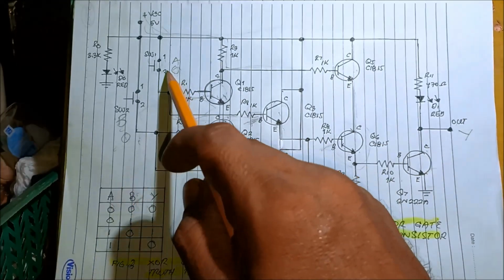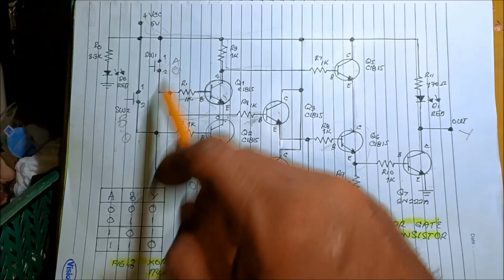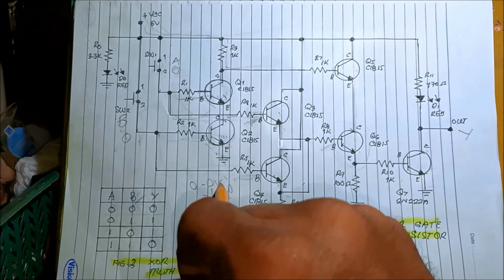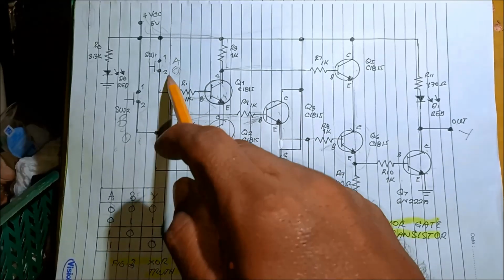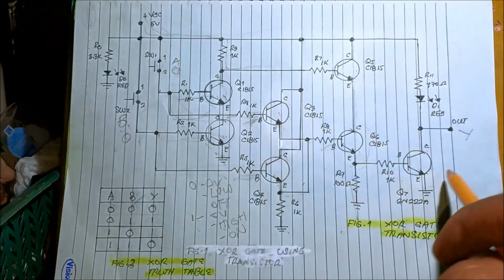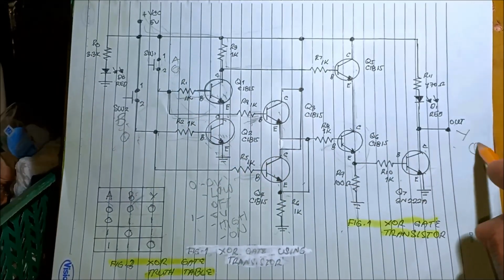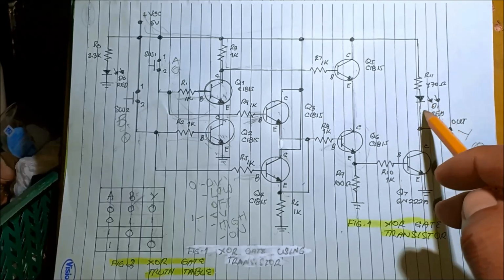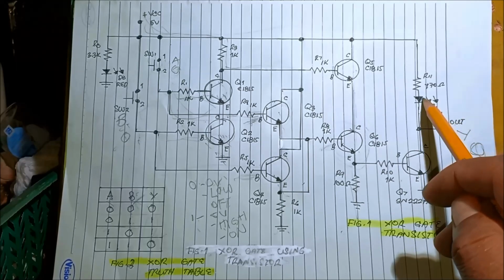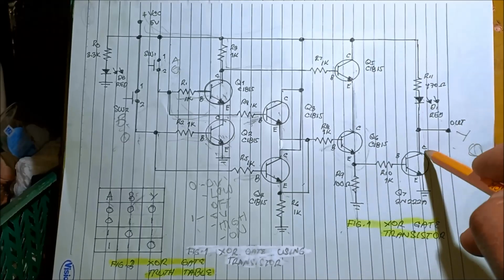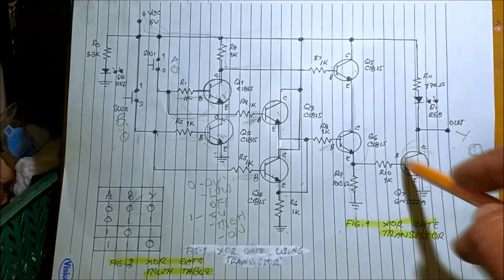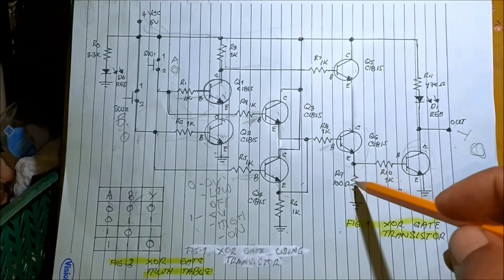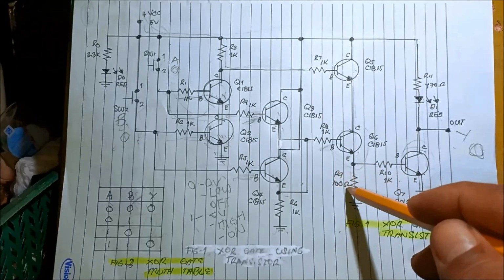That's why if the switches are logic 0, meaning 0 volts or low, 0 0, the output is 0. It means the LED did not turn on, or it is off. There's no current that flows into the collector to emitter of this transistor. I'm using this 100 ohm resistor.